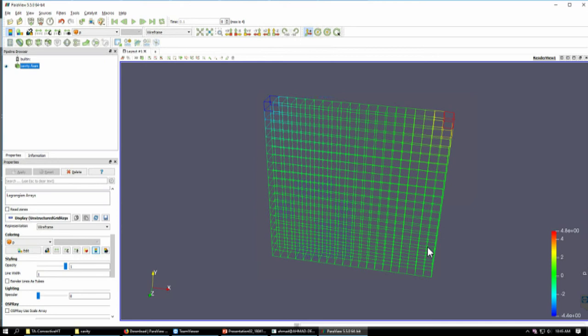So our solver calculates one value for pressure in each of these cells. So within a cell, the value of pressure should not change. If we want to have constant values of pressure in each of these cells, one value of pressure within one cell, another value within another cell, and we want a representation in this fashion, then what do we do?